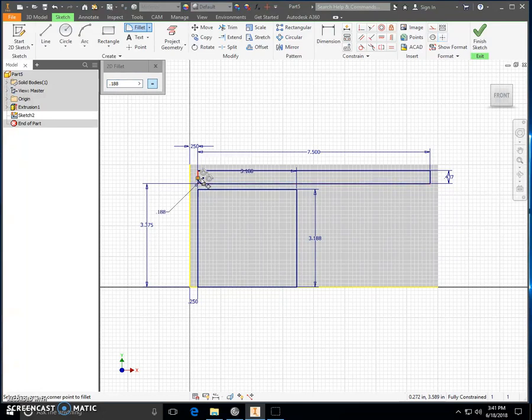Click the next line to select it. Click that line again. Click the next line to select it. And continue around your box. We also want the top 2 corners of our notepad holder rectangle. Click one side, click the other, puts that fillet in there. Click one side, click the other. And when you are finished, you can close out the fillet box. And you can see it put our nice fillets in there.